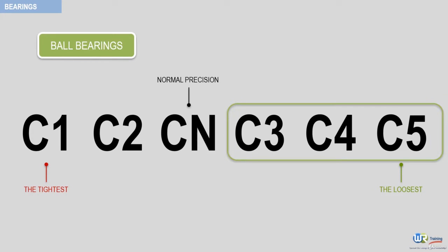With this understanding of pump bearings, you can see that it is not convenient to replace a C3 pump bearing with a C1 bearing. Because of its strict tolerance, a C1 bearing can handle less thermal expansion and lubricant contamination that occur with normal pump operation. A C1 bearing is less forgiving with thermal expansion and contamination and will fail prematurely.